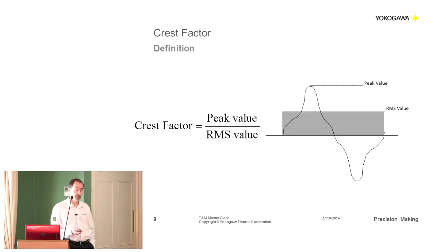So you can see that modern devices, instruments that go into standby power, for instance, where we're talking about 1 watt or even half a watt, have very high crest factors and quite low power factors as well. So it presents a big problem to the instrument you're measuring power for, because your ranging may be dictated by your RMS value, but your dynamic range must cover the peak value.